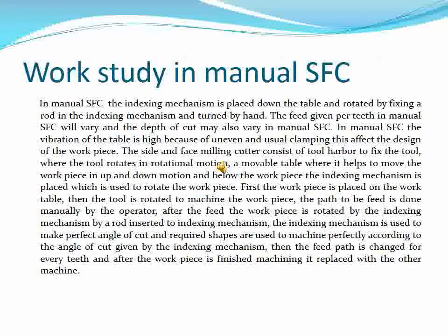In the present method, there are many difficulties and errors. In order to overcome them, a new design is proposed. This design helps to overcome the errors and difficulties faced by the operator. The proposed design consists of a tool arbor and a table to keep the workpiece, below which the indexing mechanism is kept. The movement of the indexing mechanism is controlled by the pneumatic system, which is controlled by servo motors. Since servo motors are very useful in braking, this helps the indexing mechanism to stop, and these operations are controlled by a PLC, Programmable Logic Controller.